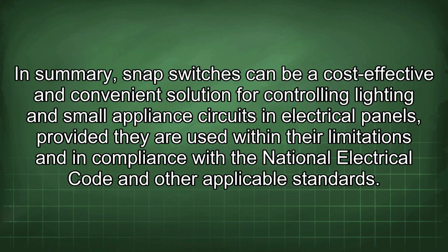In summary, snap switches can be a cost-effective and convenient solution for controlling lighting and small appliance circuits in electrical panels, provided they are used within their limitations and in compliance with the National Electrical Code and other applicable standards.